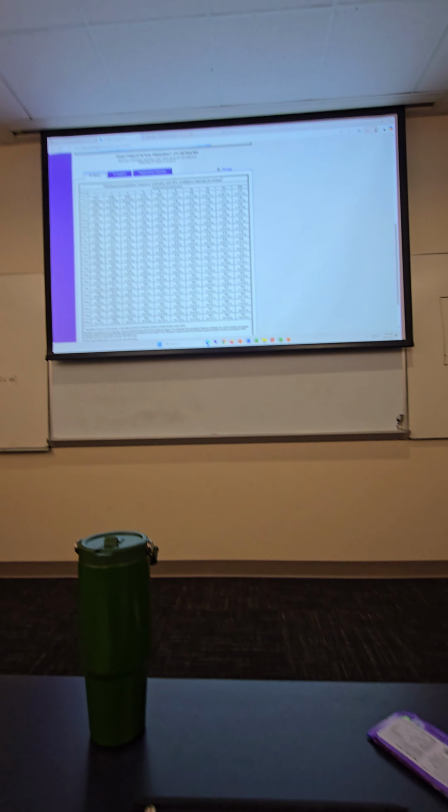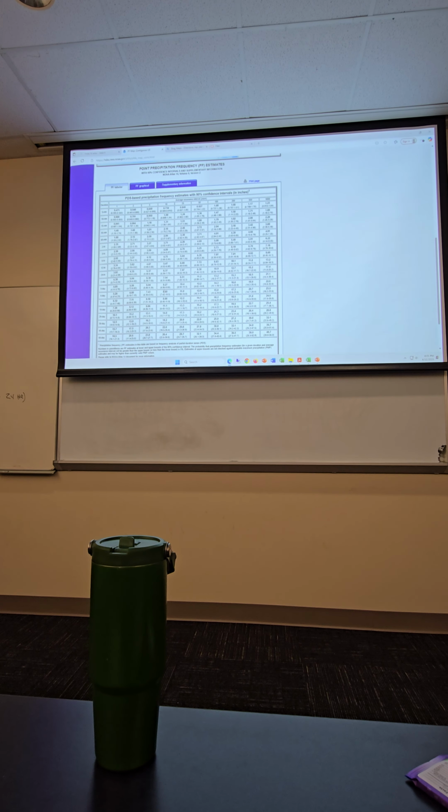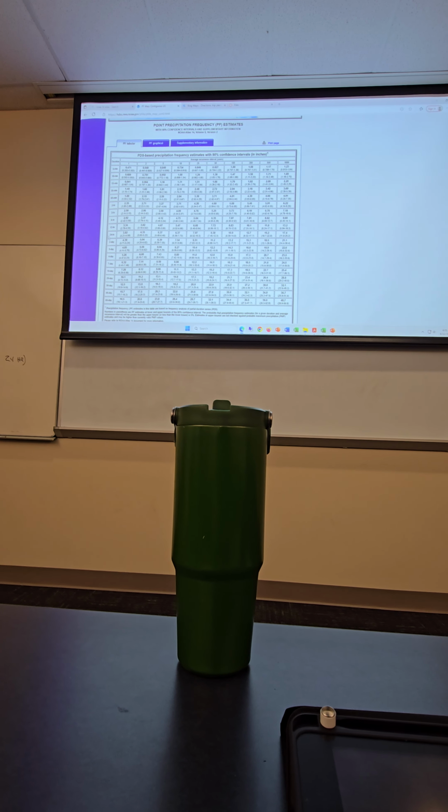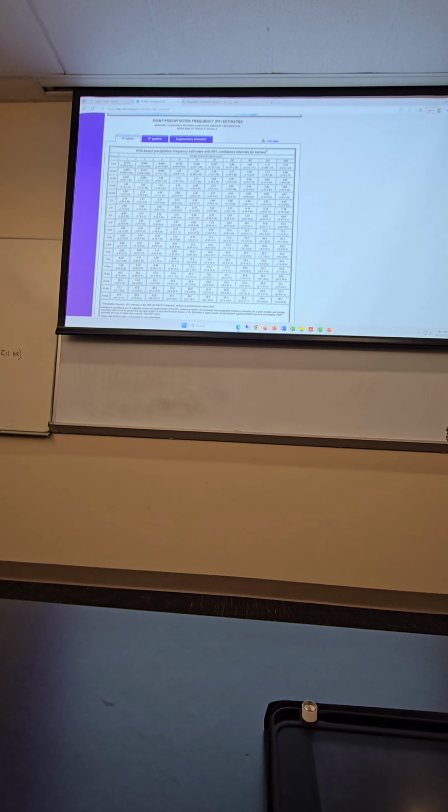In this table here is the total depth for that particular duration. So in our case, we're gonna look at a 25-year storm, and for this location, for 24-hour duration, that depth is 7.97 inches. So that's the total rainfall for that 24-hour period. Does that make sense? Okay?